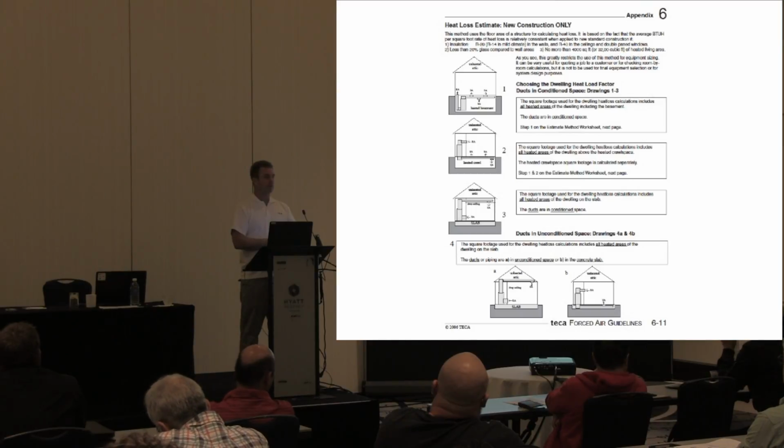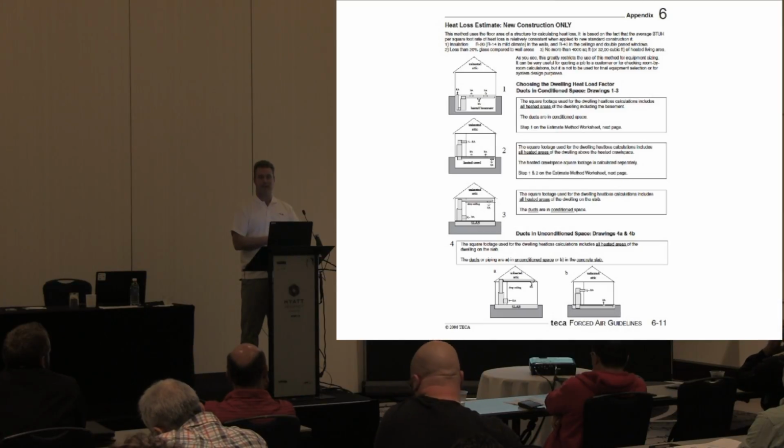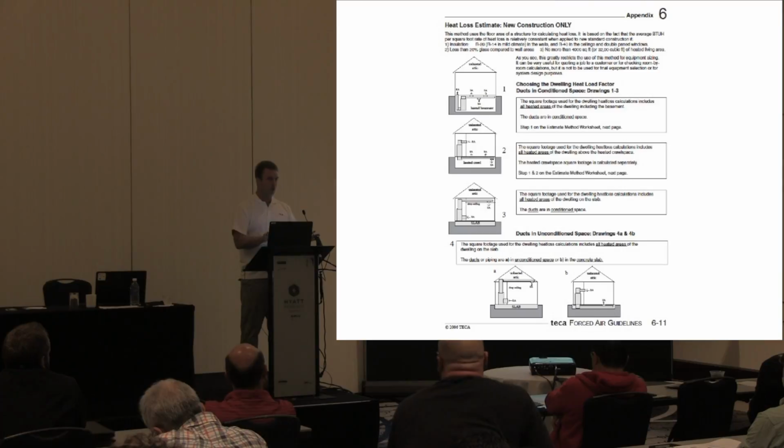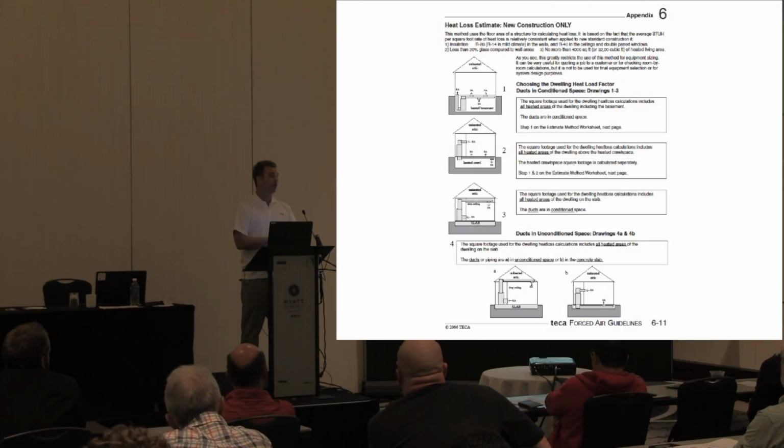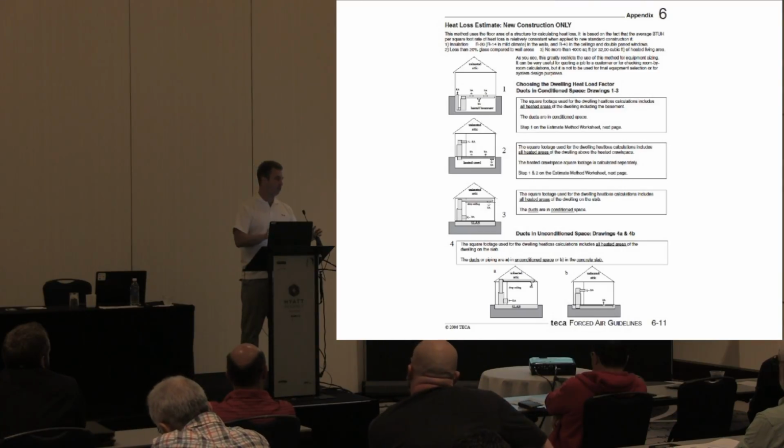What's the factor for windows? It depends on the window. A new low-E double argon window is 19 per square foot, but it depends on the window. If you're putting in triple glazed, or maybe higher end double pane windows that have a little better R value, those are things you'd have to look at. That's just a generic double pane, low-E argon window, a base, normal window.